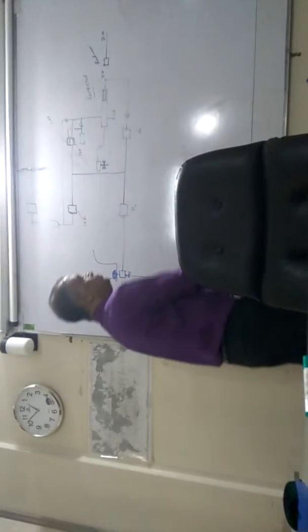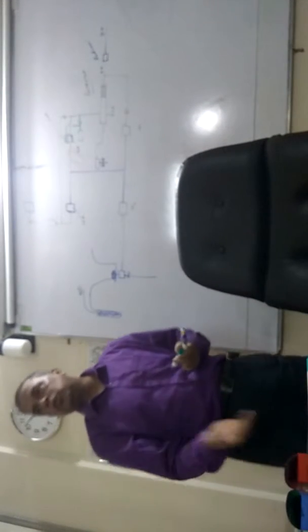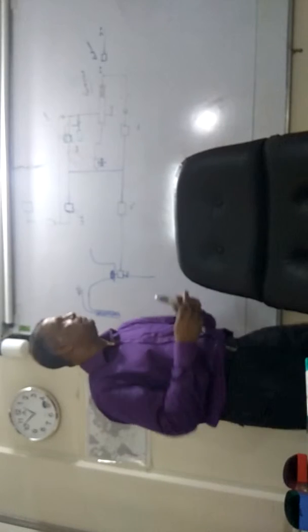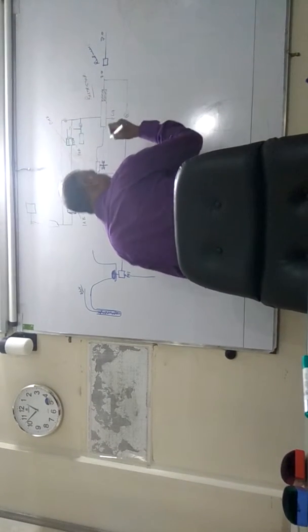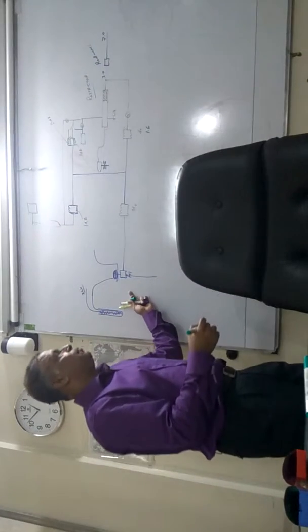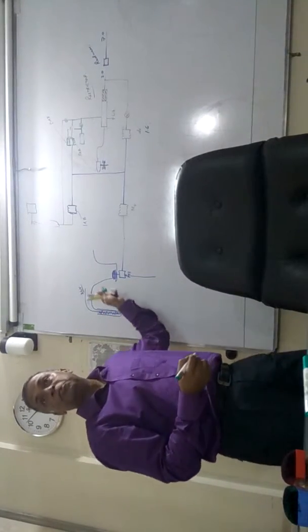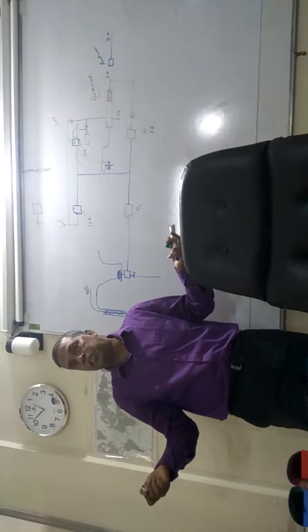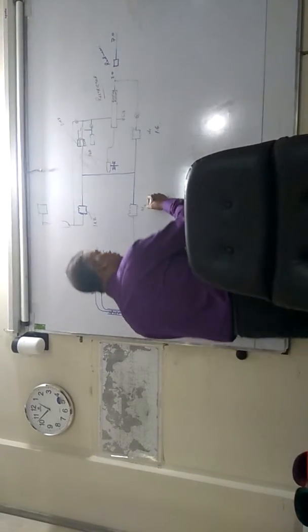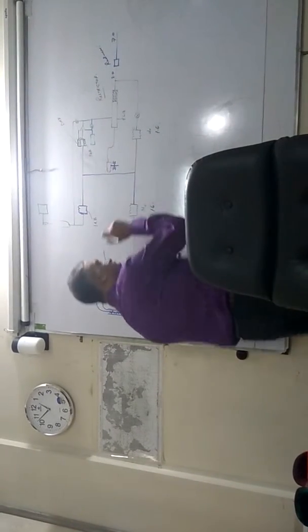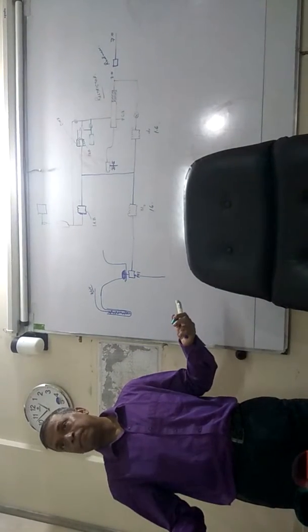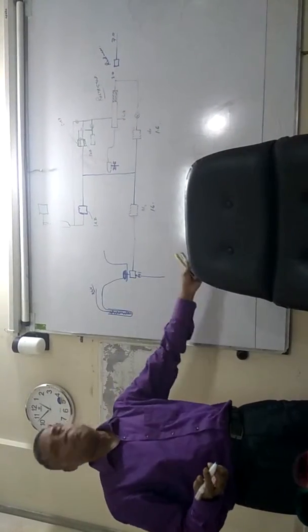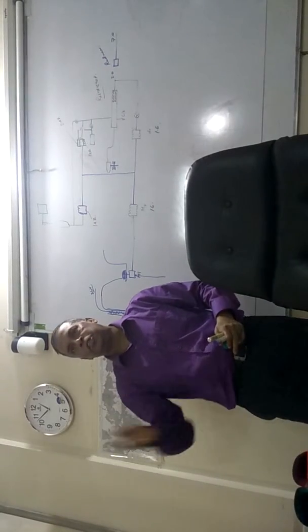Now we assume that we have fixed the dial for 80 degrees there. There is some certain pressure, say 1.6 bar, something like that. And at the point when the temperature of the jacket cooling water system was also 80 degrees C, say around 1.6 bar pressure is also available here. Okay? And our flapper is right in the vertical position.